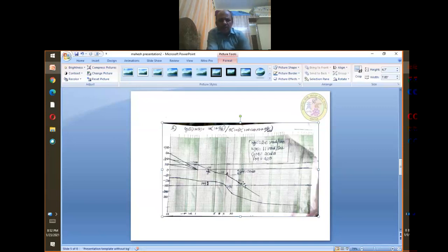So this will continue to some infinite distance. In this case, there is a quadratic pole, that will reduce the amount of vibration by 7.3 decibels. So shift it upwards to a positive value. At the same time, the quadratic pole contributes minus 40 decibels. Remember, a quadratic pole contributes minus 40. So minus 20, minus 40, minus 60 decibels. It is not minus 40 decibels, it is minus 60 decibels. At the same 11 radians per second, for the quadratic pole, the effect of zeta is to reduce the magnitude, 7.1 upwards. Then mark the angles as usual, 0, minus 60, minus 120, minus 180, like that.